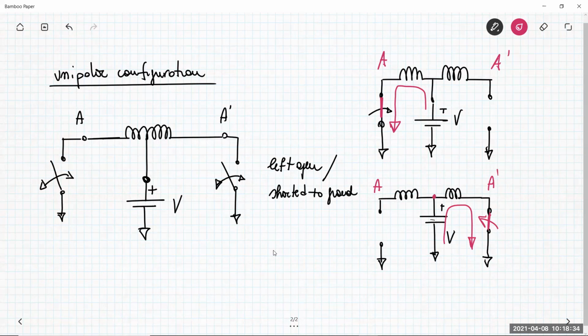So there is a current which always flows from the center common terminal to the ends, A and A prime, B, B prime, etc., but just in half of the winding. So, for example, this first situation can be exploited for part A of slide 17, and this can be exploited for phase C of the behavior you can find in the figure in slide 17.